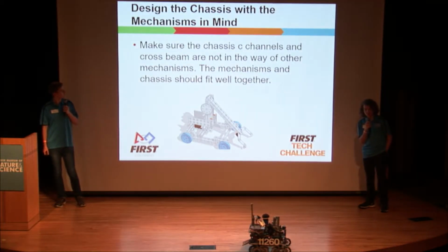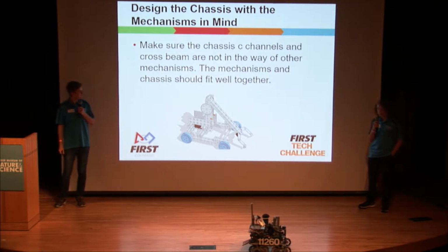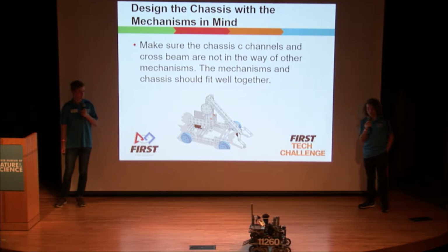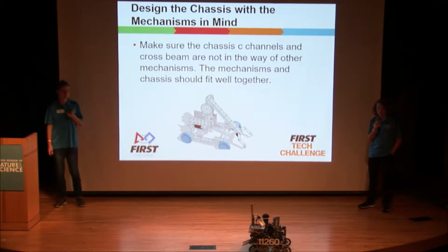So again, you want to make sure that you design your robot with your mechanisms in mind. So you don't want to put your drive motors or anything in the center of your robot where you might want to put an intake or arm mechanism.